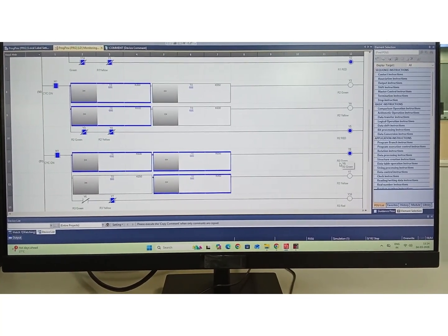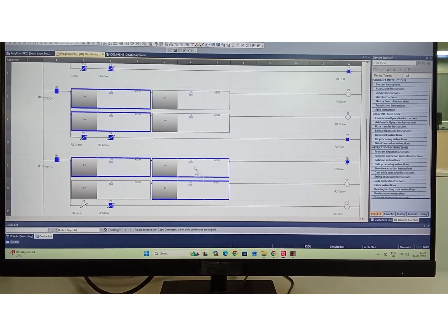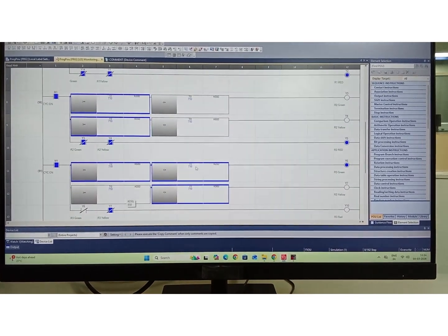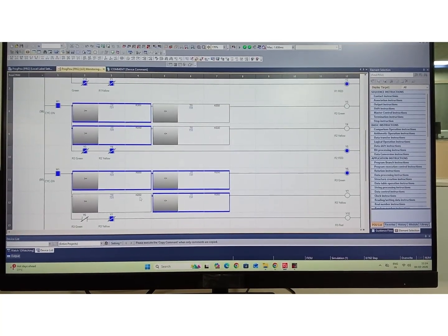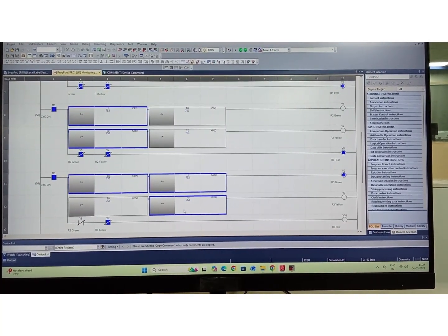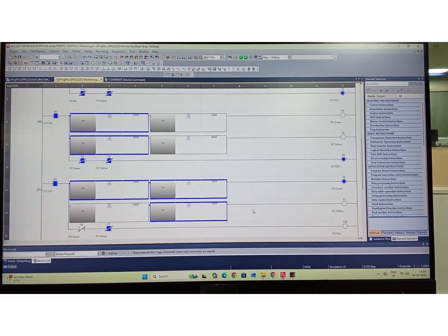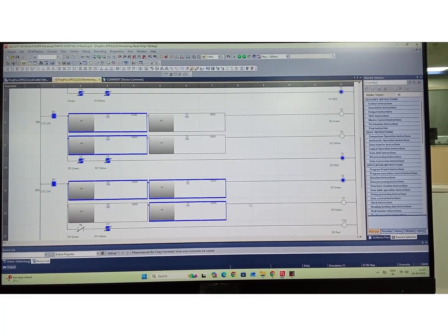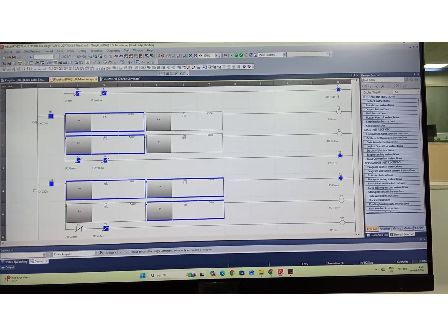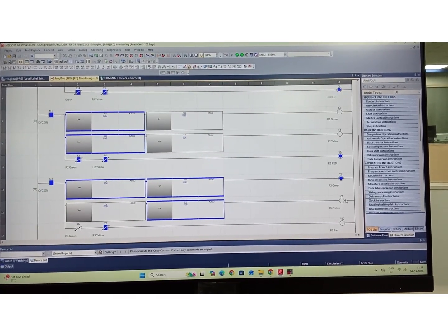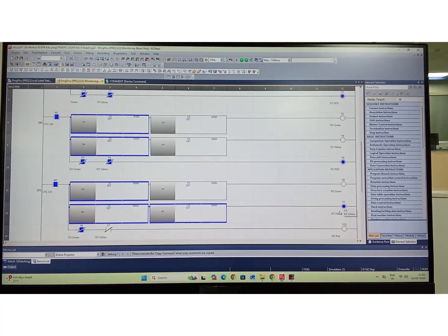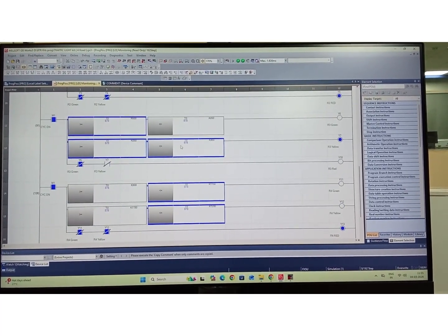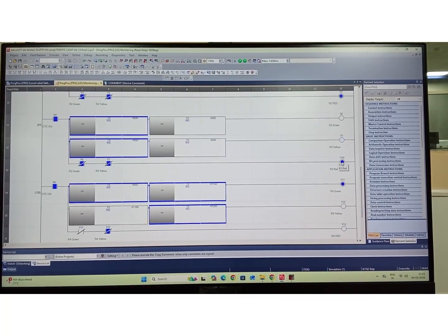So route 3 is green till it reaches 85 seconds. Once it reaches 85 seconds, it will convert to the yellow color for 5 seconds. Route 2 is also red, and route 1 is also red. So now it will shift to the yellow color. Yes, yellow. After 5 seconds, it will turn red for route 3.